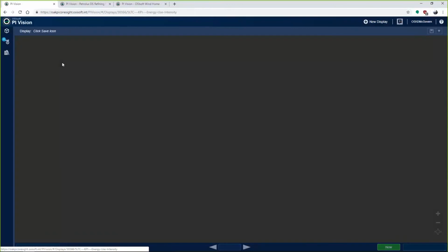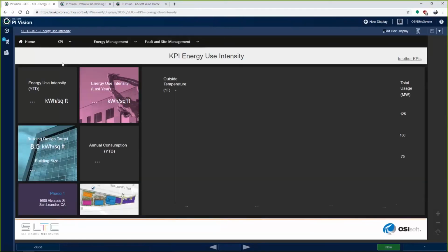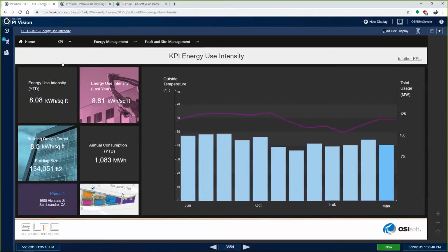and how people are reacting to the current temperature, and how acceptable that is, and what our overall energy usage is as a function of that temperature, to really gauge, okay, this makes sense. The big thing that I could discover here is if one area is both heating and cooling, and no one's really complaining because they're canceling each other out, but we're using tons of energy just spinning our wheels for no good reason.